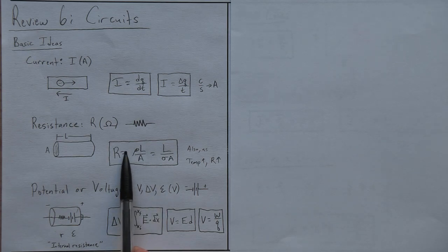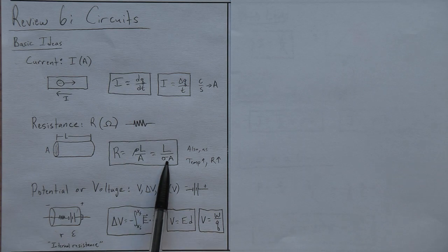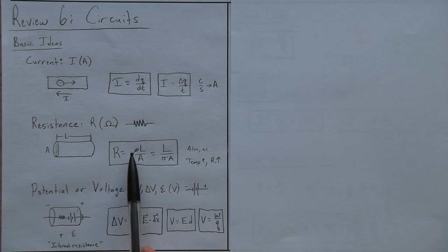Also, I talked about recycled symbols. This is the symbol for charge density that we saw earlier in the Gauss's law unit. Well, not anymore. In this topic, it's resistivity. This was charge density over an area, sigma, not in this topic. This is the conductivity of a metal. So resistivity and conductivity are reciprocals of each other. The more conductive, the higher this is, the better conductor it is, whereas the higher this is, the worse conductor it is. So this is a basic formula for resistance.